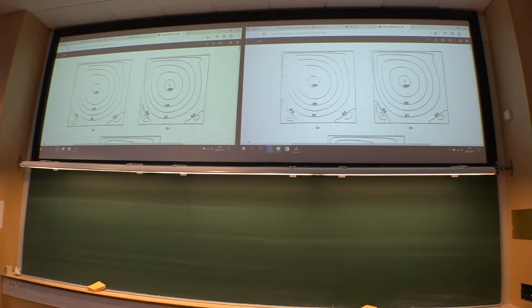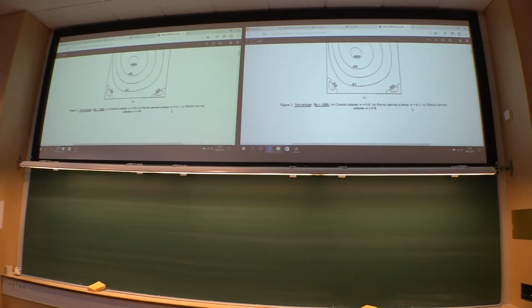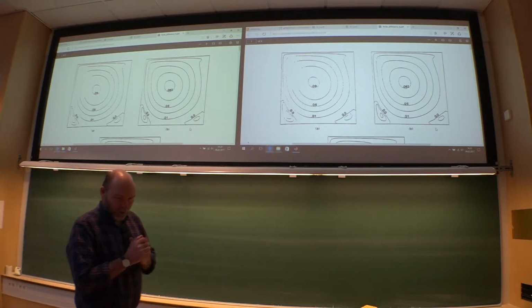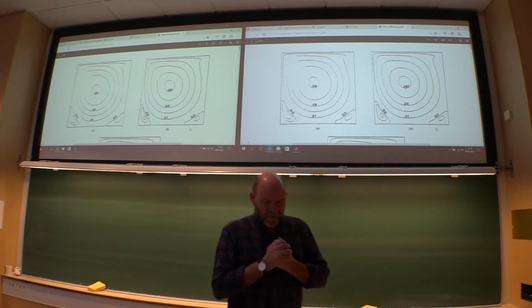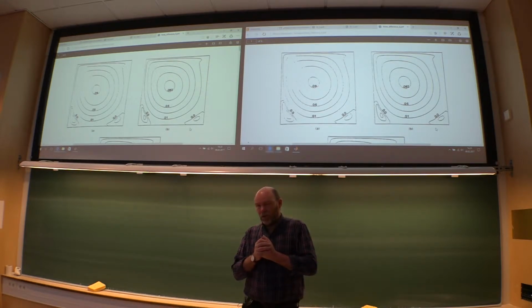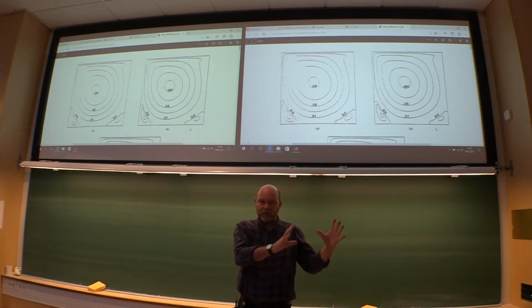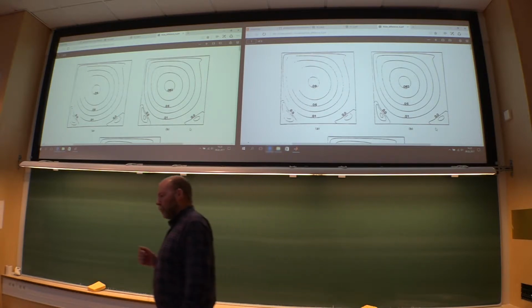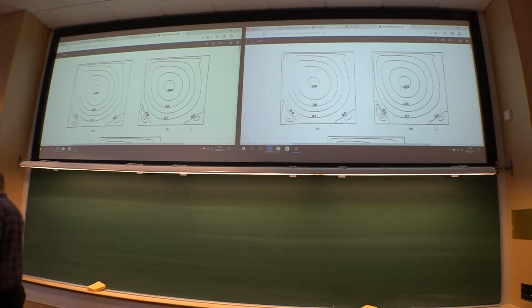To the right here, you had chosen 10% of the upwind scheme. So this alpha that we had in the previous lecture, you set alpha equal to 0.1. Then you have 90% central scheme plus 10% first order upwind scheme. You see the effect.